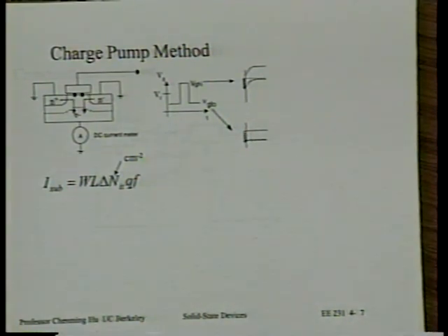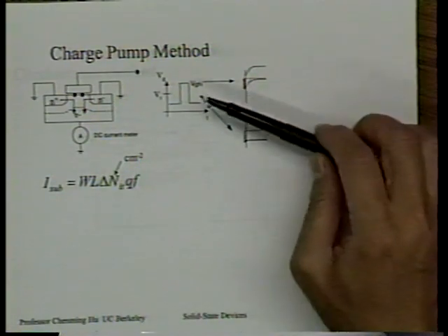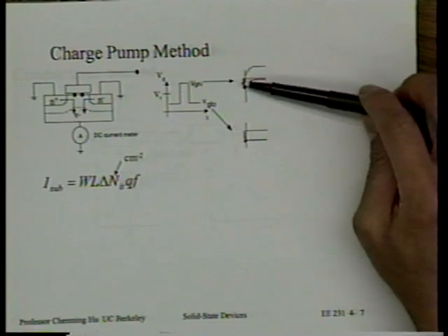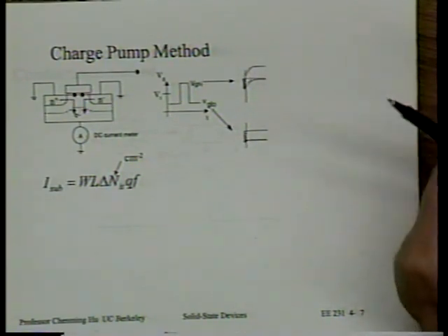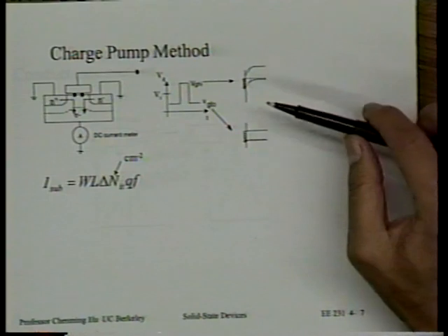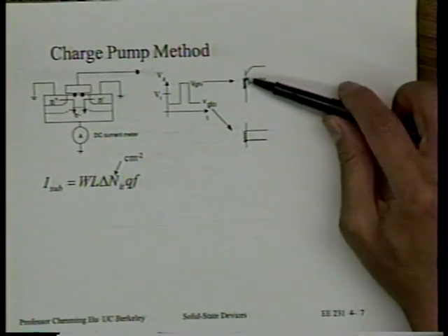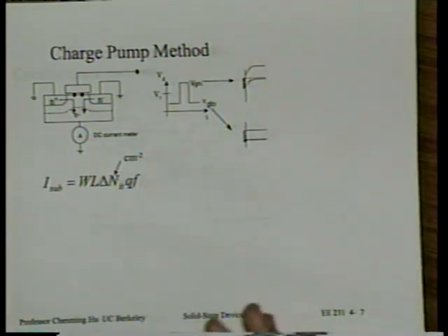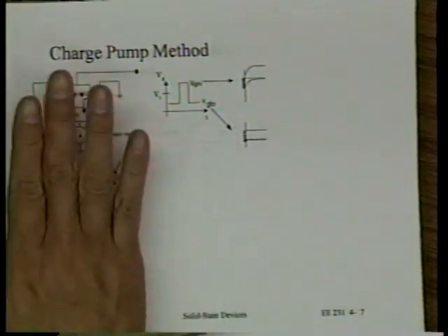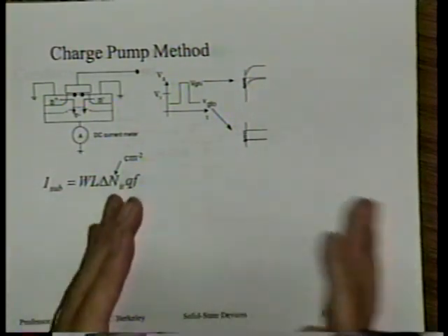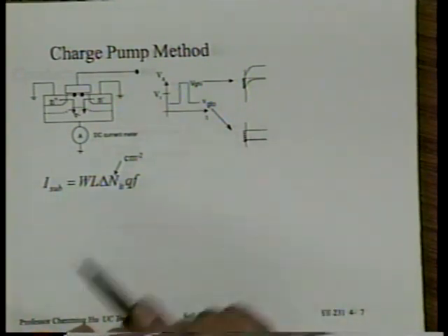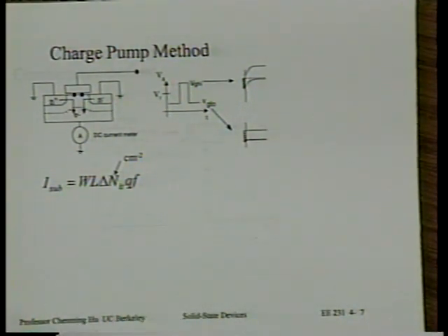If we did that, let's see what happens to the traps. When we go into the high VG, a lot of electrons come, all the traps get below the Fermi level, so they get filled, right? If there's an inversion layer, that's even better. That helps fill these traps. Even then, there's still a little time delay. So unfortunately, that's one of the limits of this technique. We're not 100% sure the traps are filled in the on state. We're going to assume that the on state is long enough so that the traps are all filled. In fact, we can say all.